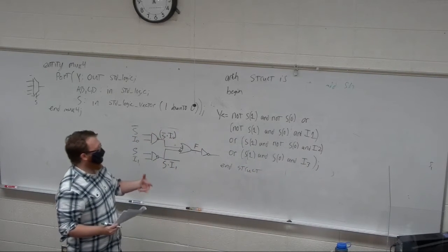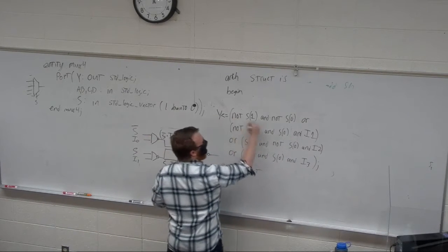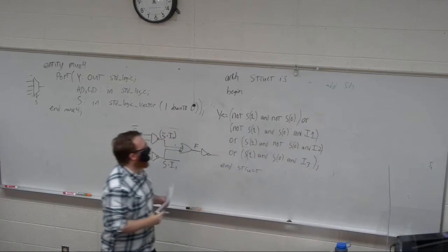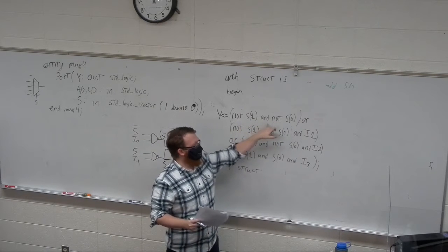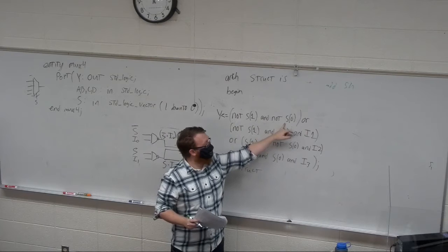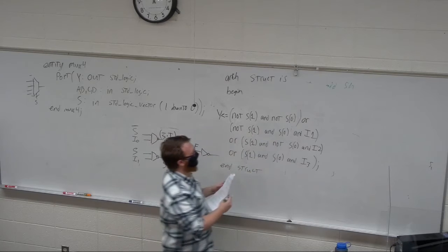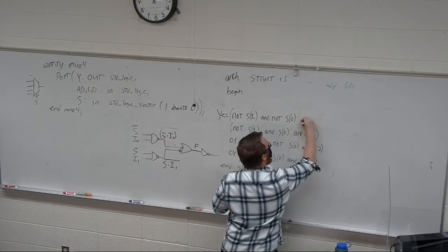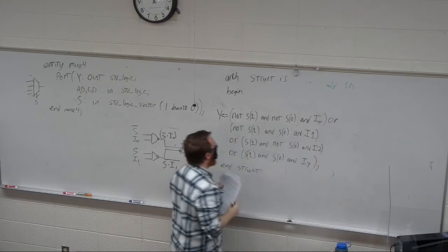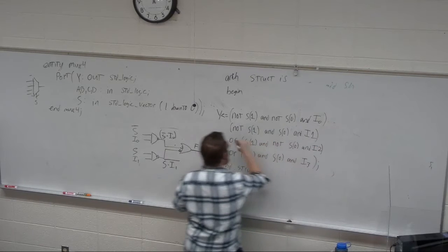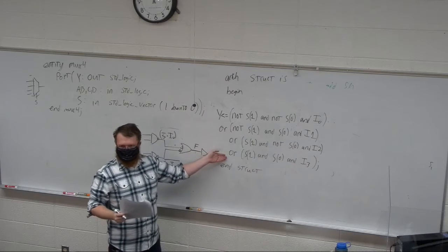Okay, so all I've done is take the gates and write them out explicitly. Oh, I probably need parentheses here, right? So if I don't have S1 and not S1 and not S0, so 0, 0, or, did I miss one on that one? And I0, sorry. And I guess for consistency, I can move this down here. So if any one of these is true, it's 1.